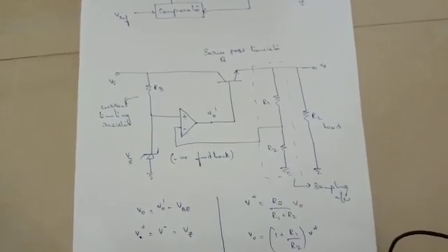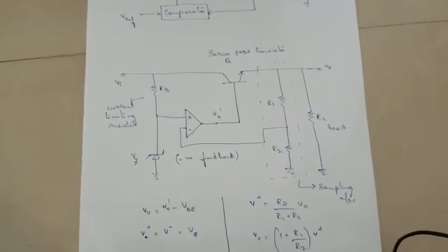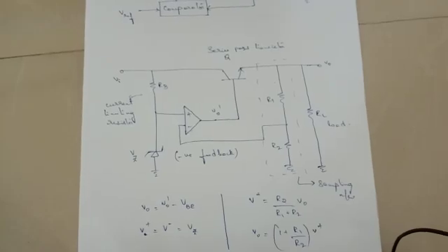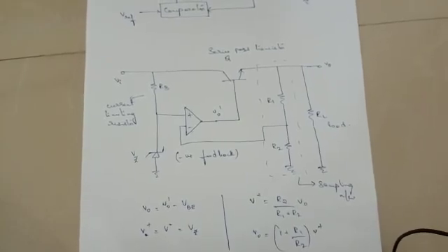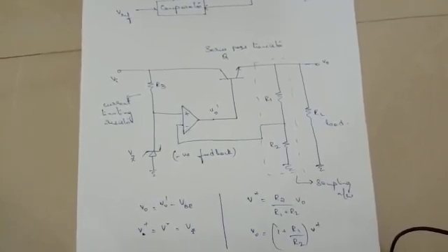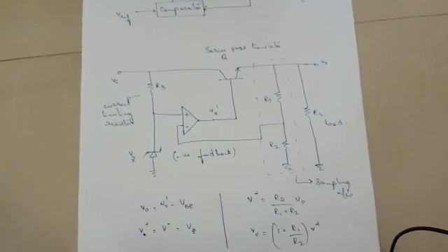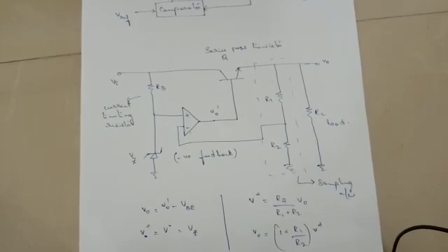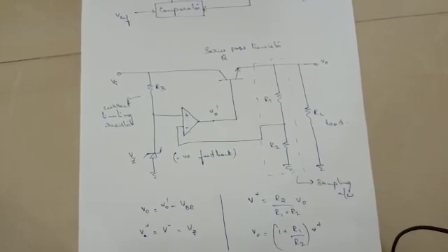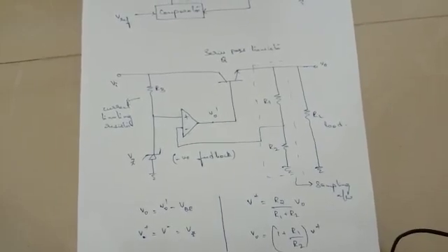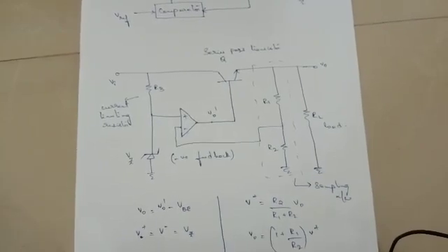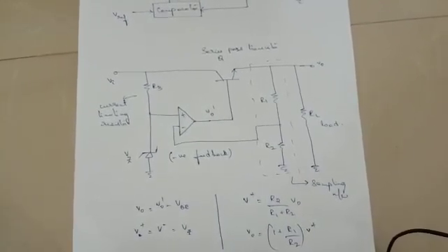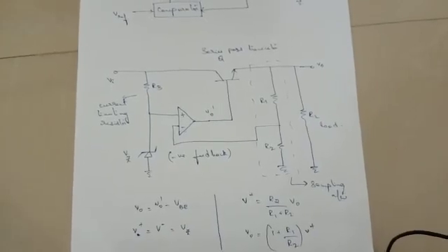The transistor gets activated once the output of the op amp remains positive. The output of the op amp produces initially a positive voltage because of the unregulated input signal which is developed as a reference voltage across the Zener diode. Therefore, once the series pass transistor is in the on state, the input signal is transferred to the output. This creates load current across the resistance RL, which creates a voltage drop V0.